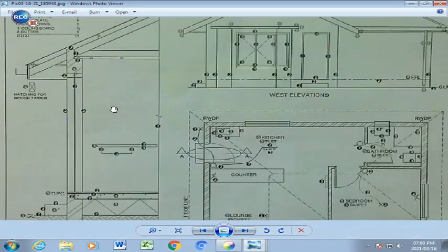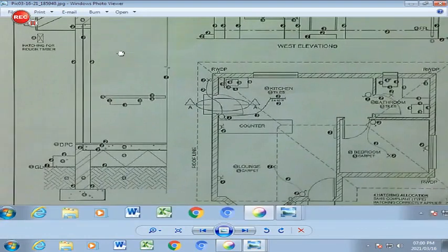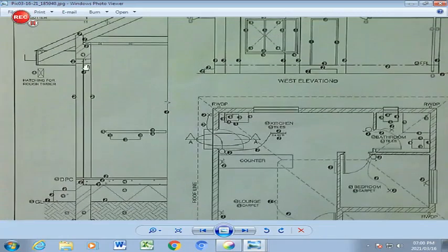So here we have our section elevation, and you start with the given foundation here. You draw up your wall, you add your various slab levels, all divided by 20. Very importantly, that slab goes halfway into the wall. Then you have your screed there, and the screed runs into your DPC. Don't forget to put your concrete step here, which is going to be 300 by 200, all divided by 20. Then you add your door into your wall.